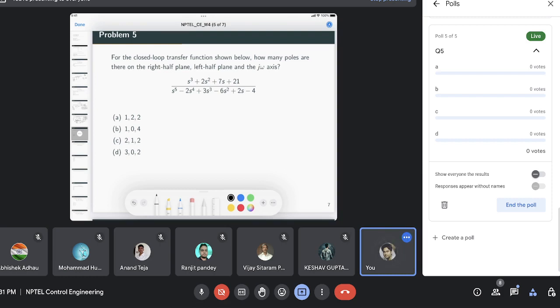And if a row of 0 happens, you count how many right half plane poles there are for this auxiliary equation, and symmetrically how many left half plane poles there will be for it, and the remaining will be the imaginary axis poles, right?